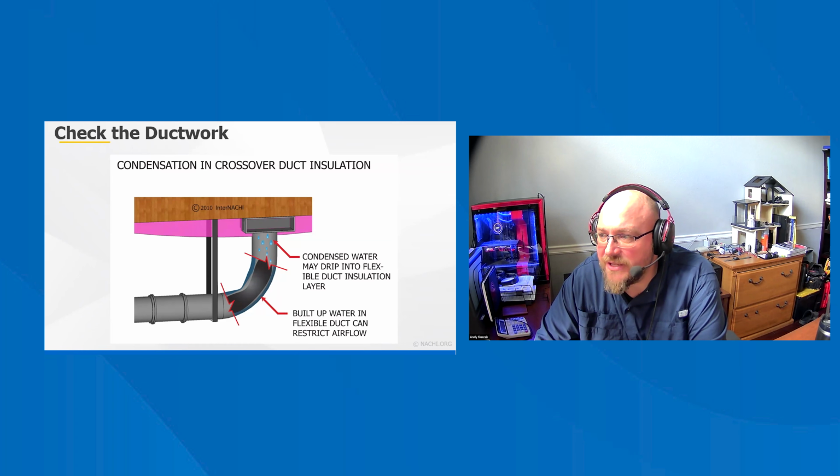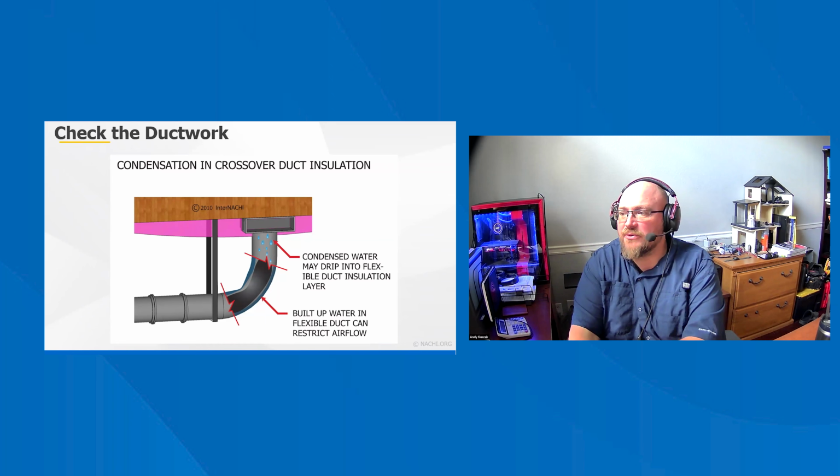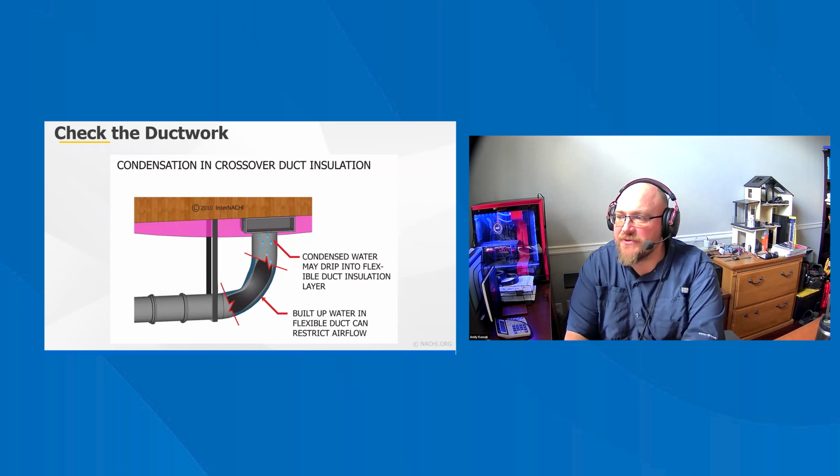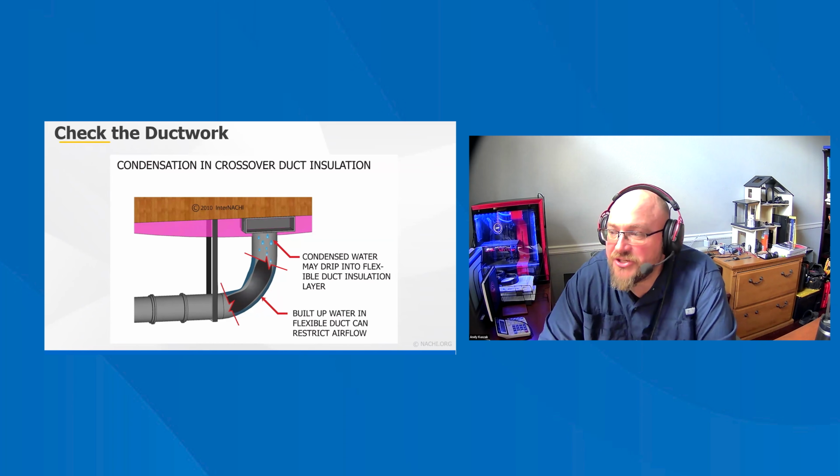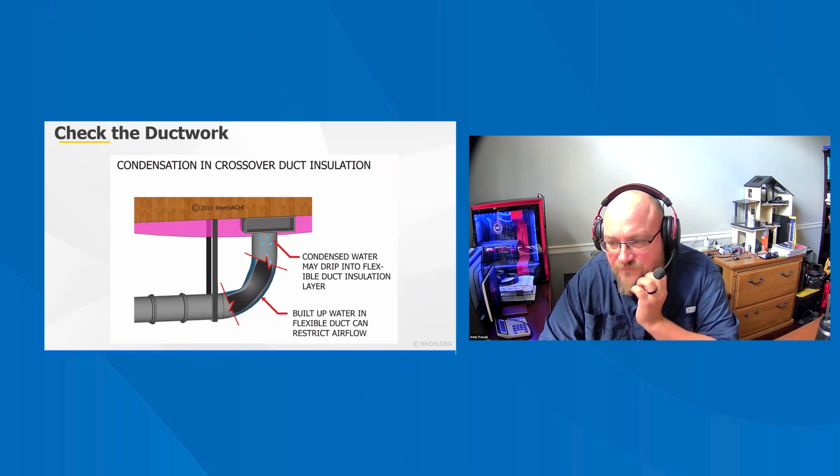If the joint is going to be opened up in the future for maintenance or other reasons, then aluminum foil tape may be used. The ductwork should be wrapped with insulation that has a minimum R value of 6, with a vapor diffusion retarder facing on the outer exterior side. The insulation should not be compressed. It should be overlapped and sealed with fiberglass tape where sections of the insulation meet. The insulation should not be torn or damaged. The vapor diffusion retarder should not be cut, torn, or damaged. The ductwork should not be compressed or damaged.